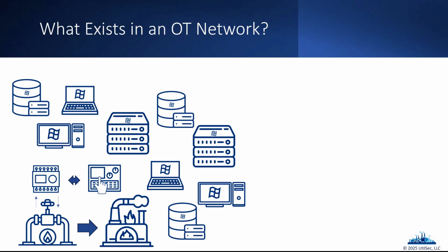Because then we have to realize, well, what is this type of system? What's at this one IP address? Oh, it's a PLC. Oh, that's great. Well, what exposures does that PLC have? Oh, it's running Modbus. Oh, I can connect and I can read these values, but what do these values mean? What type of programming or logic is actually running on that PLC? That's everything we have to go through this process to reverse engineer.